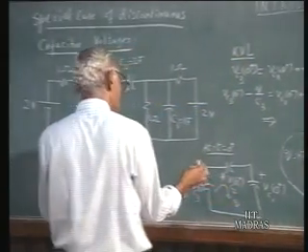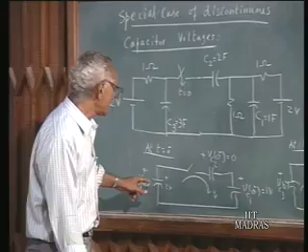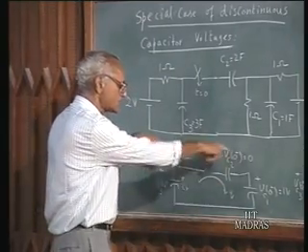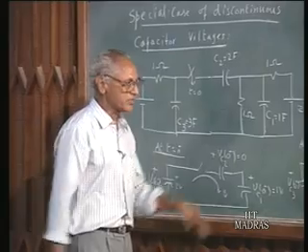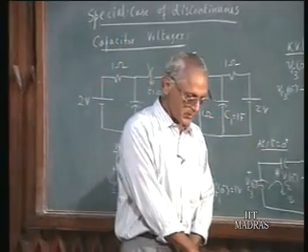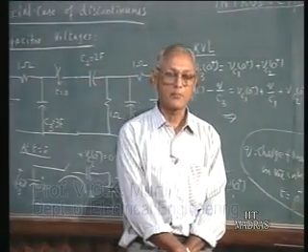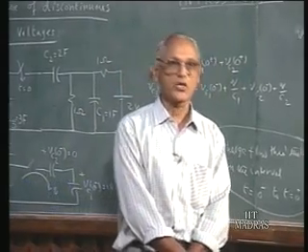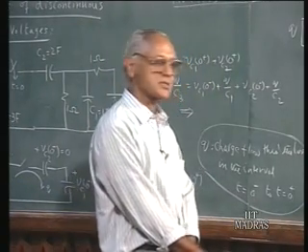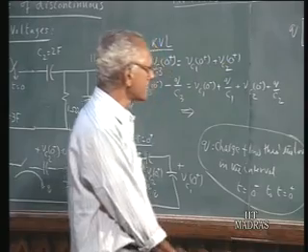What we have really assumed here is that as far as the capacitors are concerned, the charge is conserved. Whatever is discharged here goes to charge these two. Therefore this is just like the principle of conservation of flux linkages as applicable to inductors, which we discussed earlier. This is the principle of conservation of charge across the capacitors. So we will leave this discussion at this stage.